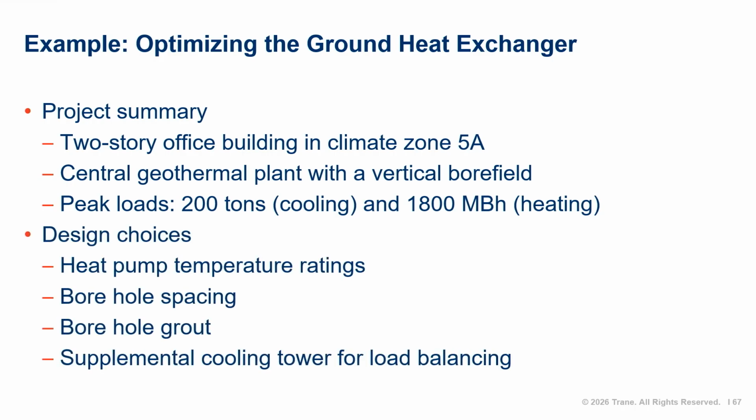Today, we'll consider the impact of using heat pumps with wider operating temperatures, changes to the bore-to-bore spacing, the value of specifying a premium grout for the boreholes, and whether adding a cooling tower to supplement the heat rejection to the ground would help. For each of these choices, we're looking for reduction in the Borefield install cost, and we're thinking about potential trade-offs against the long-term system performance.